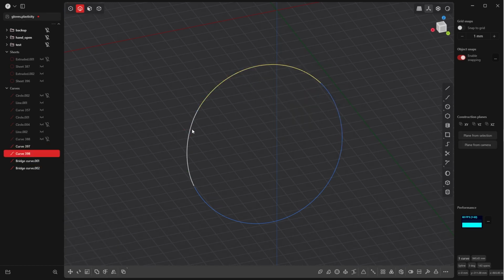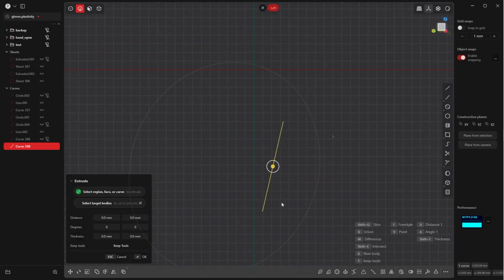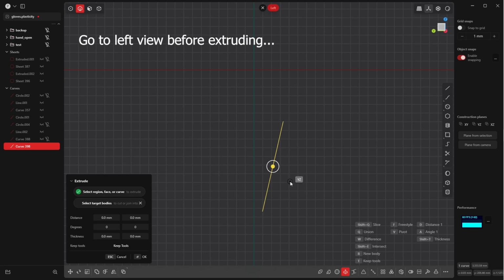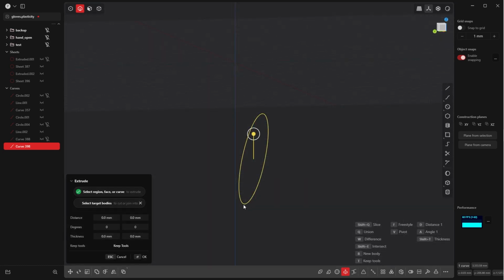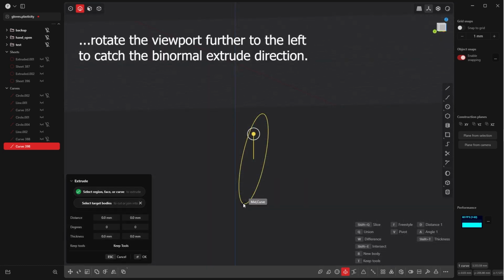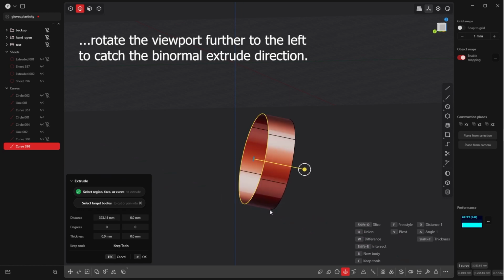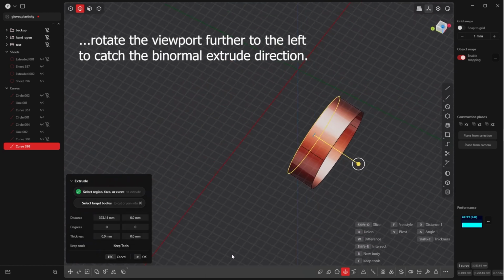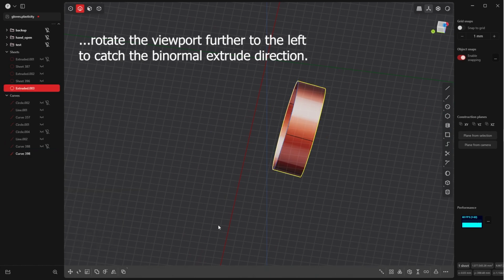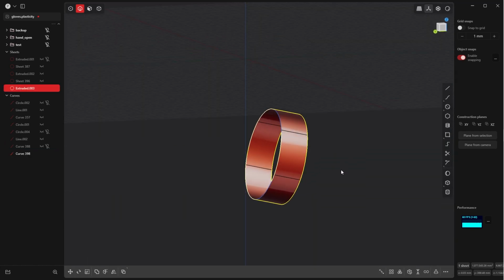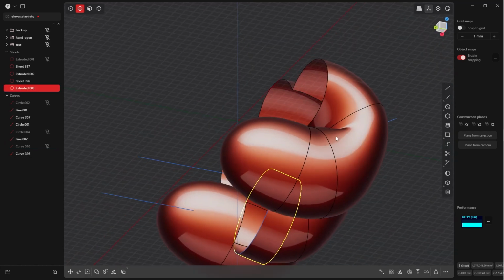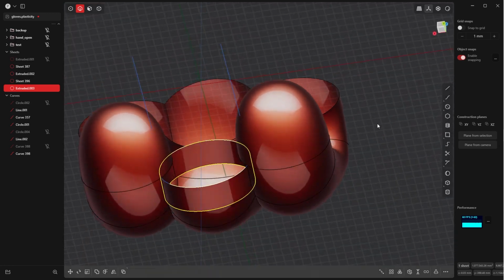Go to edge mode, select all these guys, press J for joining them, E to extrude, F to extrude freestyle. Again, try to extrude, F. Here it is. Okay. And if we bring back the rest and just check if we are fine, yes, we are doing good.